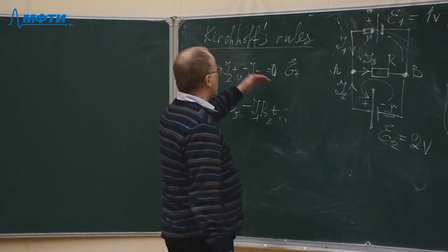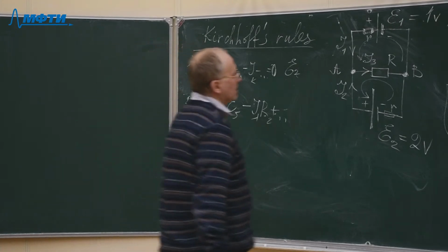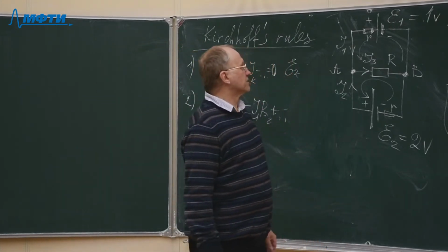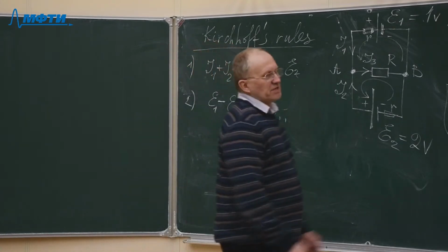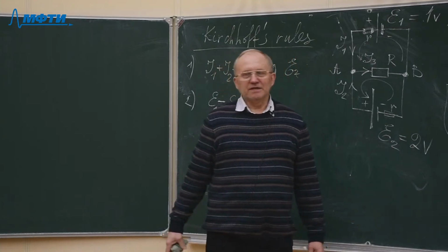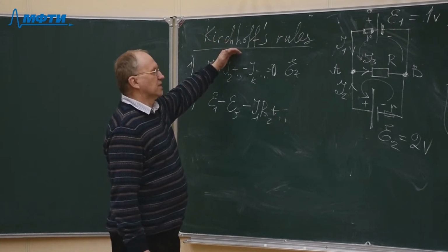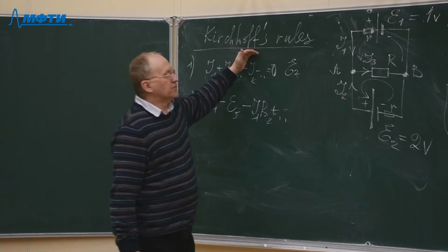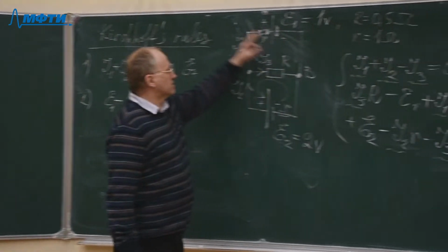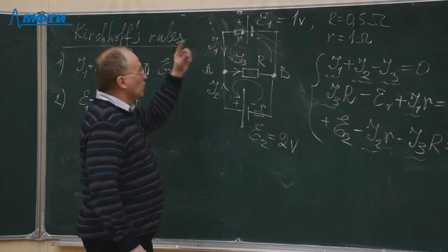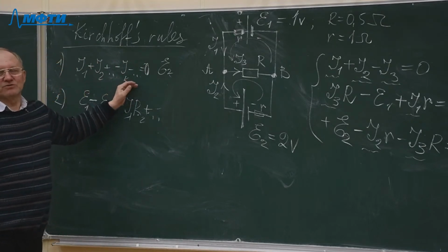Do Kirchhoff's laws work in all cases? No, certainly not. Any law of physics, any rule in physics, has a limited domain of applicability, and the same is true for Kirchhoff's rules. Kirchhoff's rules work only when you have steady, direct currents in your circuit. If you have alternating currents, then Kirchhoff's rules, strictly speaking, do not work.